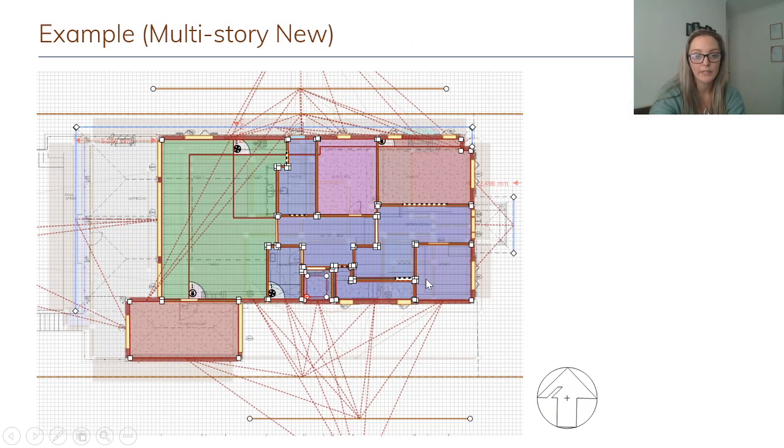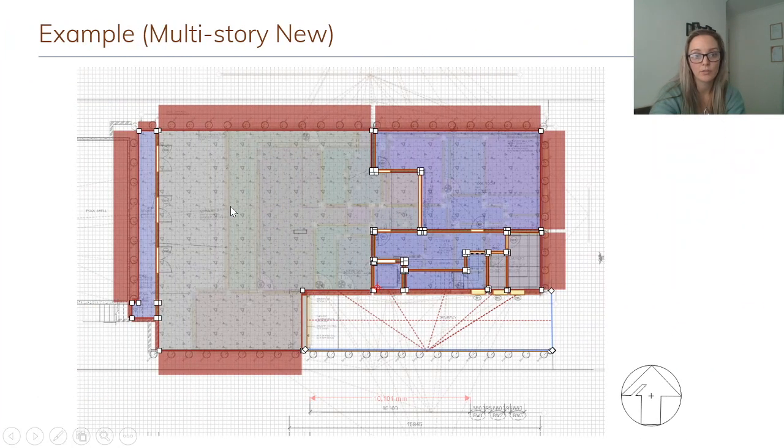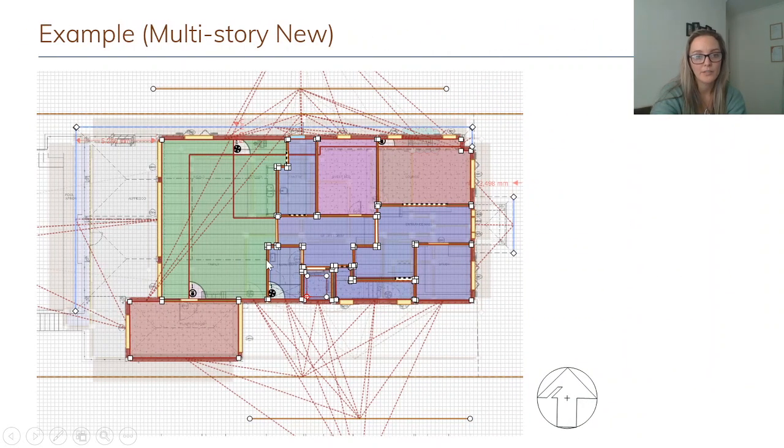Next level up is the living area. So the green area is the main living zone. And all of these different colours have got different occupancies assigned to them. So the garage is obviously not occupied. These areas here are assumed to be occupied from, I think, 7 in the morning until 10 or 11 o'clock at night. The main living area is assumed to also be occupied between 7 in the morning and 11 o'clock at night. However, this also takes into account additional heat gains from cooking.